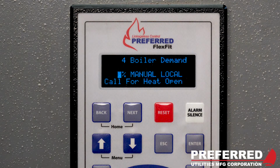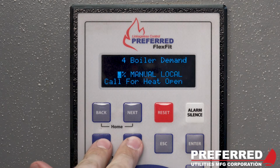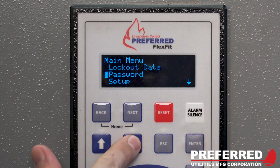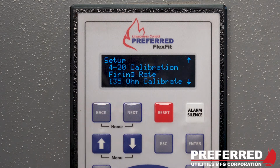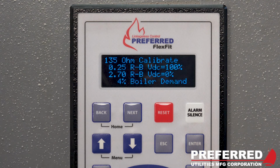To access the 135 ohm remote firing rate demand calibrate feature in the FlexFit combustion controller, we need to get into the main menu. Here you see the FlexFit combustion controller front panel. To access the main menu, press the up and down arrows at the same time with the word menu underneath them. Once here, you're going to scroll down to Setup, and from there to 135 ohm calibrate. We're now in the 135 ohm remote firing rate demand calibrate menu.